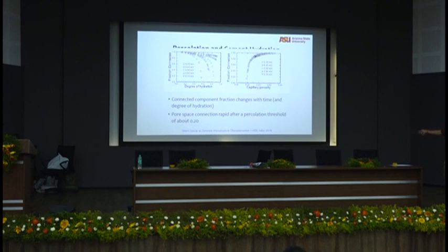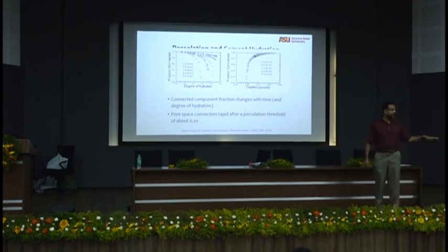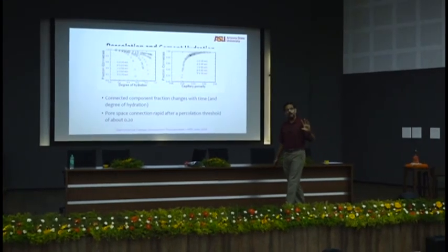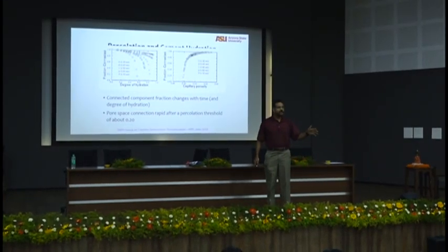0.18 for all the solids connected, even then you will have about 18% porosity. Get the idea? So you are effectively never going to completely avoid capillary porosity in concrete. So try not to attain the unattainable.